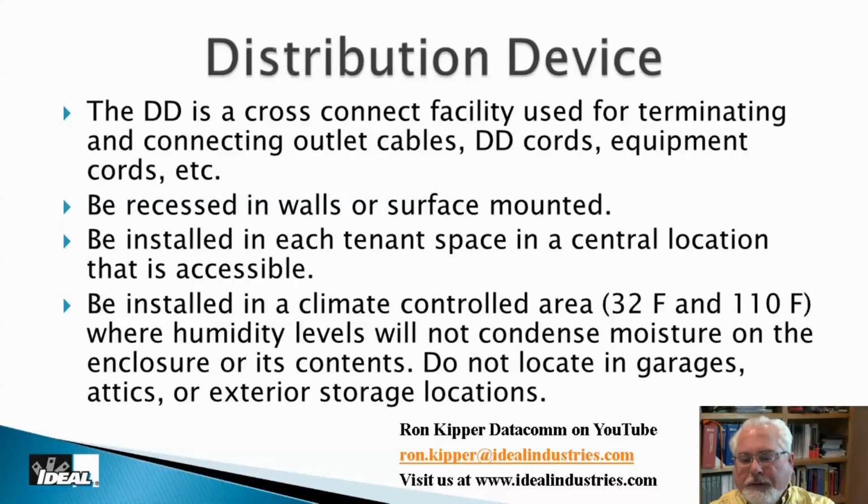By the way, the entire world has gone to compression coax connectors, and why have they done that? Part of it is because they have O-rings in them, and they can provide a certain amount of water tightness. So we like to put them in climate-controlled environments, folks. No attics, no garages, or again any exterior storage type locations. There are a number of different types of panels available to you, but we typically find these in closets, master bedroom closets, mud rooms.